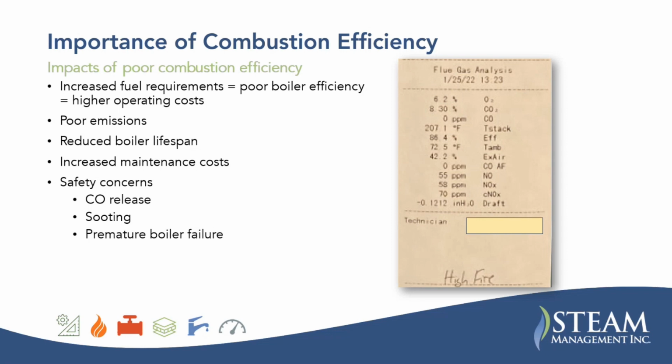You could have carbon monoxide release due to poor combustion. You can have sooting in your boiler, which leads to hot spots in the boiler, which leads to premature failures. And those can always cause a safety concern. And premature boiler failure, yeah.